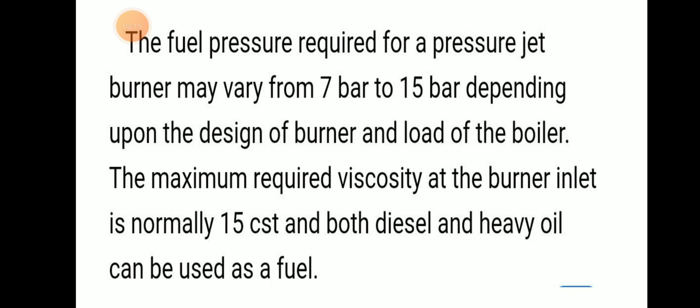The maximum required viscosity at the burner inlet is normally 15 cSt, and both diesel oil and heavy fuel oil can be used as fuel.